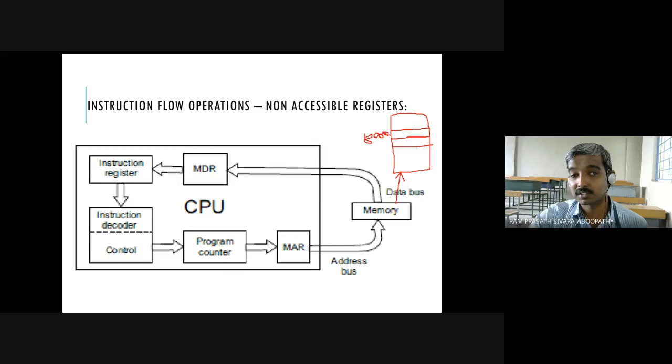Okay, this is 8000H. That means a 16-bit hexadecimal value. Clear? The next memory is 8001H. So for the example I just mentioned, we can write 3E here. Clear? In the next memory, what am I going to write? 37. Okay, kindly observe. This diagram indicates only the instruction flow. This, combined, we call an instruction: MVI A, 37H.